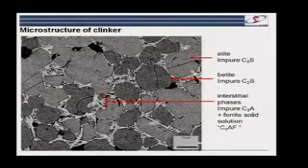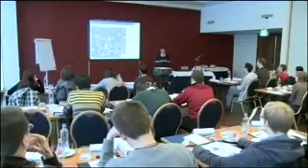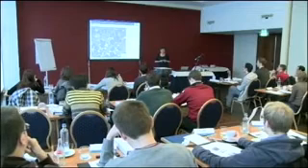And then in between, you've got the material that was liquid originally, and this is now solidified to give us 2 phases. The very bright one is the ferrite phase, and in between, this is the aluminate phase. Okay? So this is basically what we end up with as the clinker. Anybody, any questions so far? No?